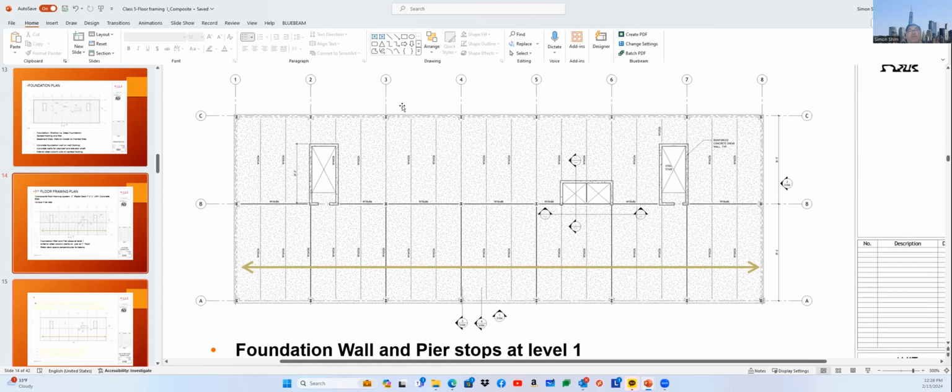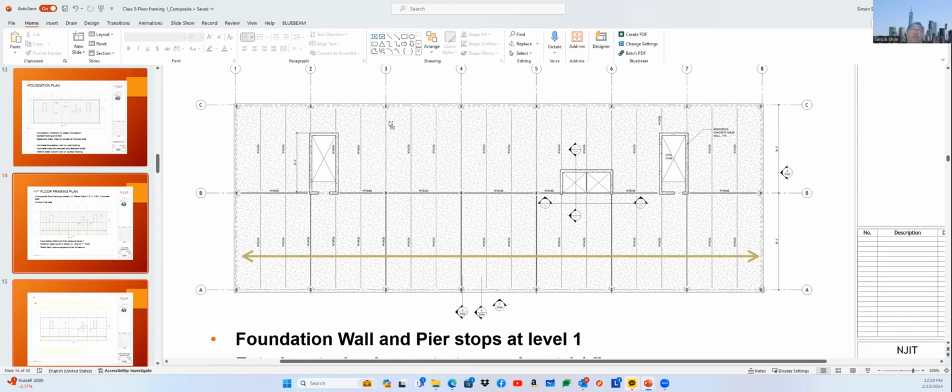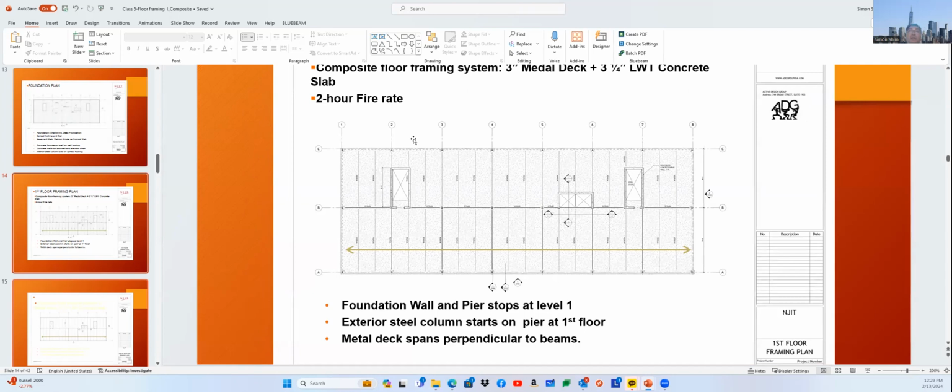If you end up with a 10 feet spacing of the column, I think you're going to end up with two beams, 10 feet spacing, okay? So you need to follow 10 feet because sometimes maybe a student actually drew too many beams, which is not necessary. Also, the reason why I highlighted 10 feet is because I want you guys to use your project as part of your portfolio. I wanted to show that your project follows general practice, so that gives you the general understanding, proving your understanding of high-rise building design.